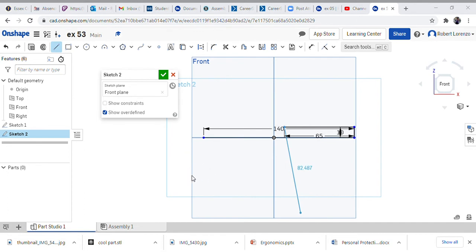So to go from the center to this outer edge is another 25. So from the very bottom to the top, we're at 75 millimeters. However, remember this thickness was 10. We're starting up here, so we can take 10 off. So we're going up 65 from the point we're at. So we're going to go up 65.